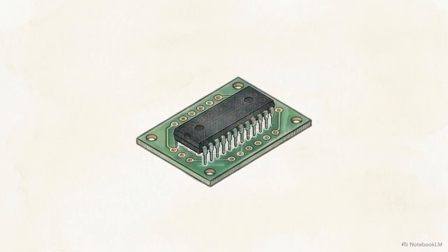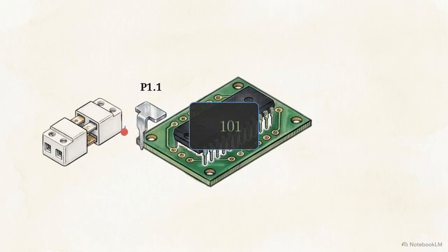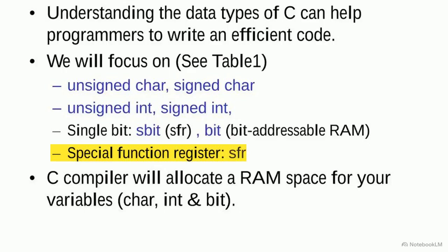which covers the majority of basic loops and counters. Internal counters are useful, but the door sensor prompt requires us to monitor the voltage state of a specific physical pin and output a frequency on another. For this, we look to the SFR data type, enabling C code to directly address 8-bit hardware registers in RAM. Even more precise is the sbit, or single-bit data type, granting bit-addressable control over individual I/O pins.